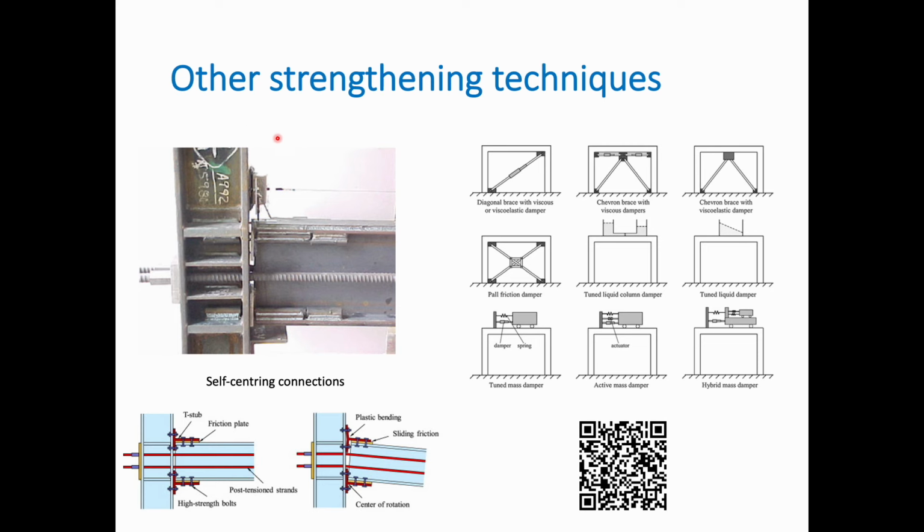Efficient buildings, and you can see here on the top left some steel shear plates like we discussed before, but with penetrations in order to define a particular buckling shape and the ductility of that system. There are other kinds of braces which are not BRBs in particular, but they act as BRBs because there are elements in tension and compression at the same time. There are, again, ways of strengthening the column by weakening the beams, creating a fuse kind of plate, like the seismic link, but this is not for a braced frame, it is for a moment resisting frame.